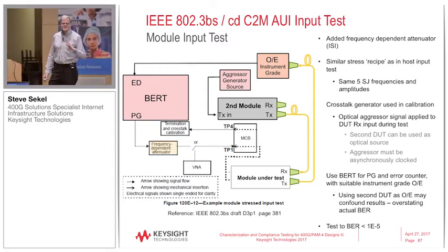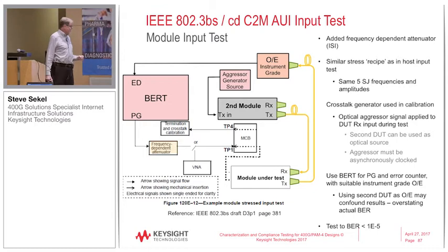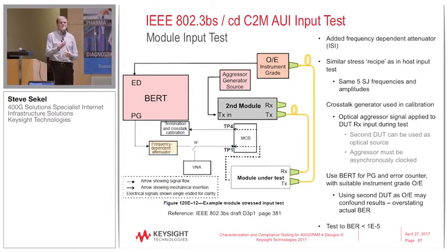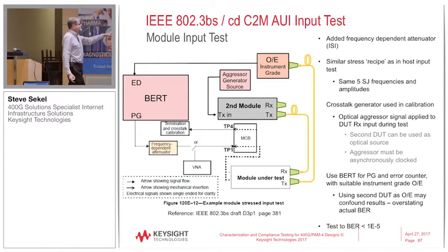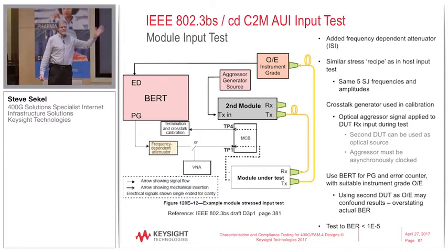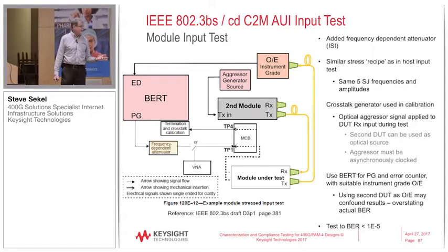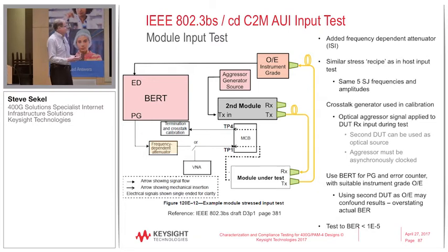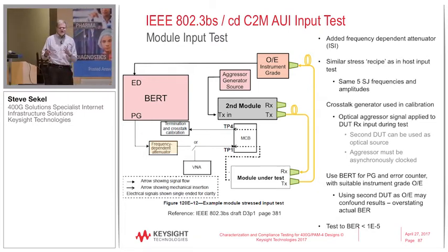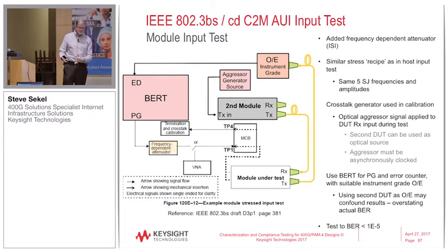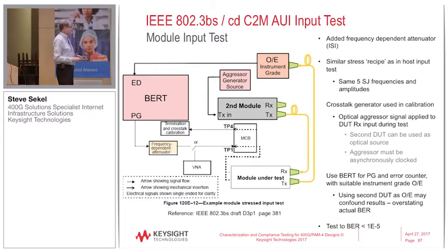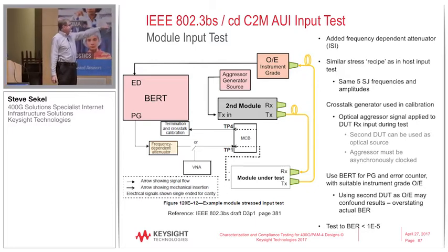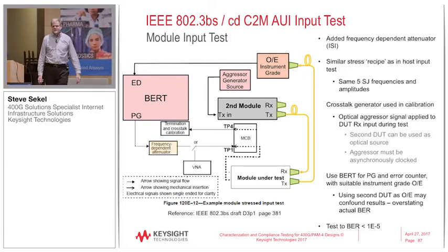Don't do that, because what I was talking about in answering Darren's question, remember with PAM4, the transmitter is part of the corrupting mechanism. So if you try to do that, it's quite likely that you're not going to make a compliance measurement, because we assume an error budget of what the distribution of error is, what percentage comes from, or what contribution of that BER number comes from the transmitter, the channel, and the receiver. And the transmitter is a healthy part of it, and more than likely, putting it through a second link, you're not going to make the BERs.